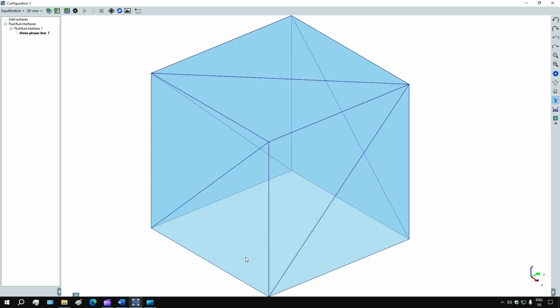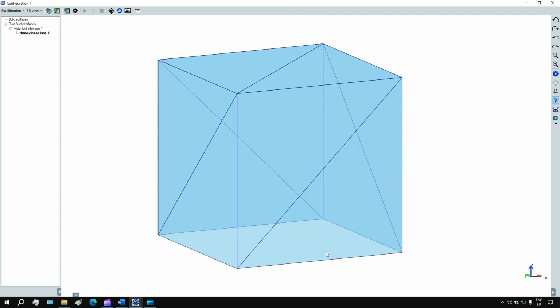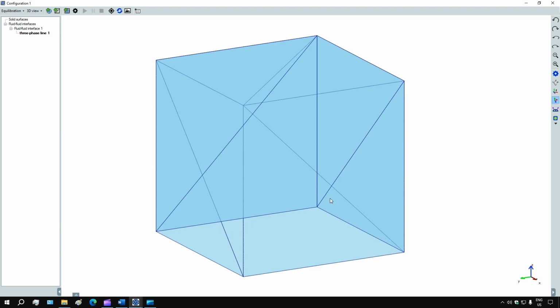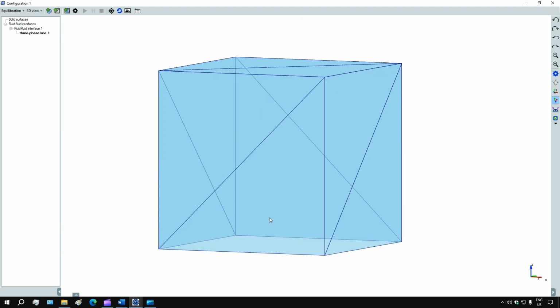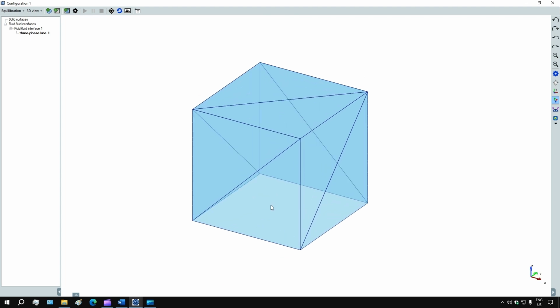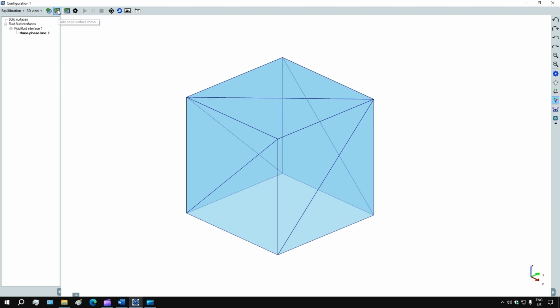This is the triangular mesh you just loaded. It has the shape of a cube, but without the bottom face, which is a correct topology for the fluid-fluid interface we want to simulate. To define the solid substrate that is wet by the droplet, we'll load another triangular mesh to represent such a solid surface, by clicking this button.